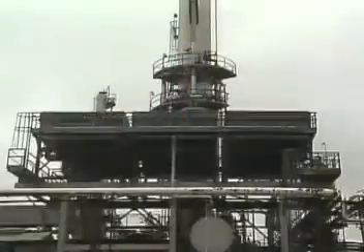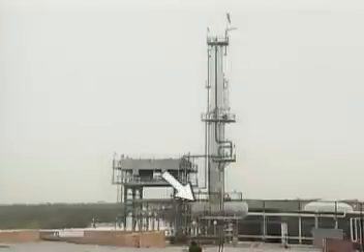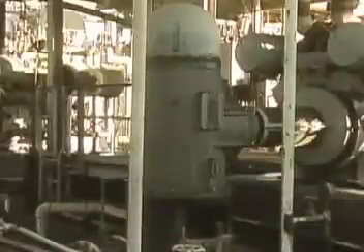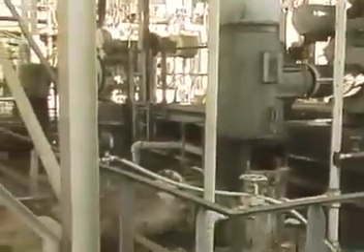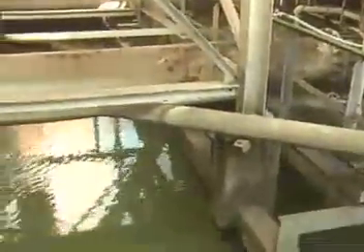One type of condenser that uses air to cool vapors is a fin fan or forced air condenser. During operation, motor-driven fans blow air around tubes in the condenser. Vapors from the tower flow through the tubes. The air absorbs heat from the vapors, causing them to condense into a liquid. The liquid or distillate then collects in a receiver. Water can also be used as a cooling medium. The water in a water-cooled condenser has the same basic function as the air in a fin fan condenser.